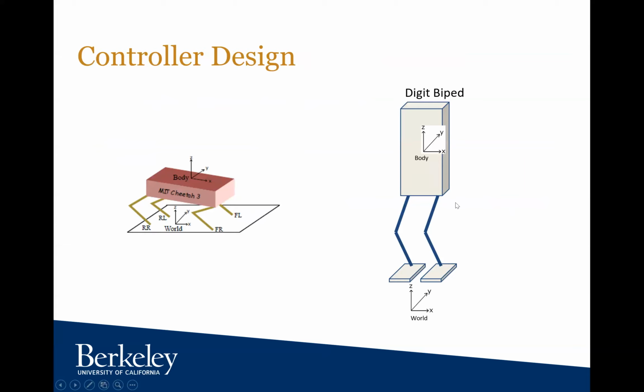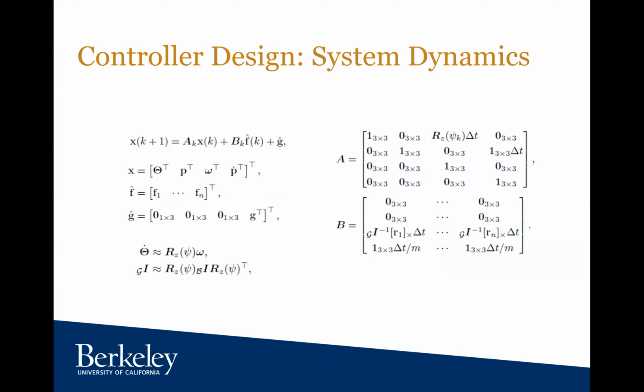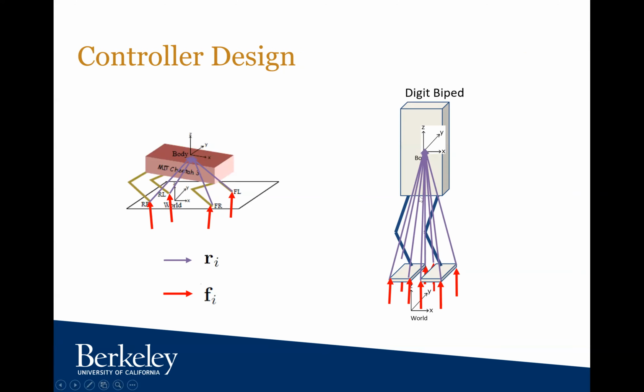Using the above assumptions, we can simplify the system to a rigid point mass centered at the robot center of mass. For the quadruped, there is a moment arm per leg that is fed into the MPC from the state estimator. Then, shown in red are the required reaction forces for each leg calculated by the MPC in order to achieve the desired trajectory for the center of mass.